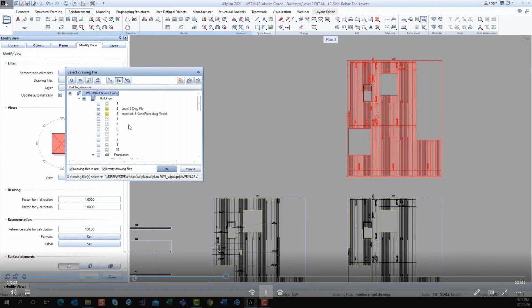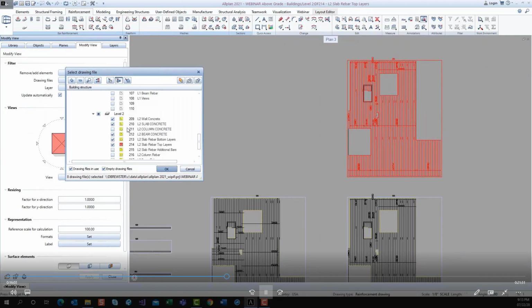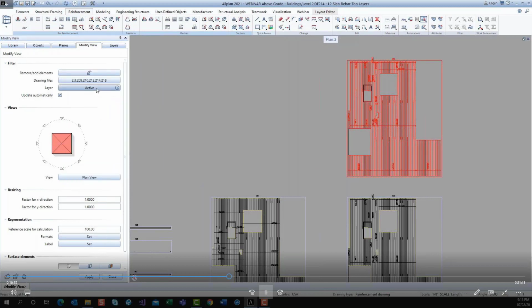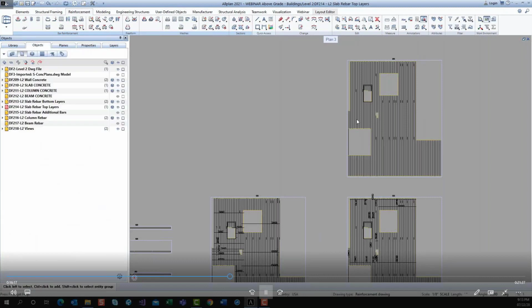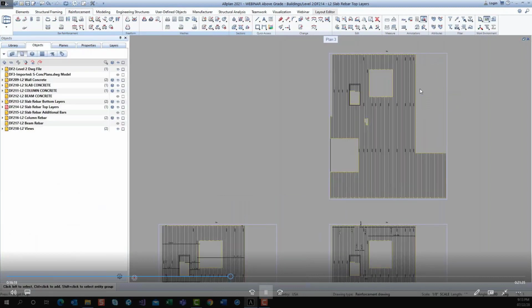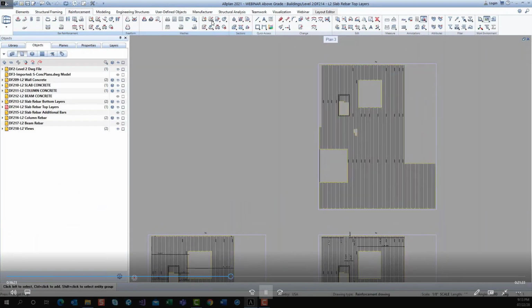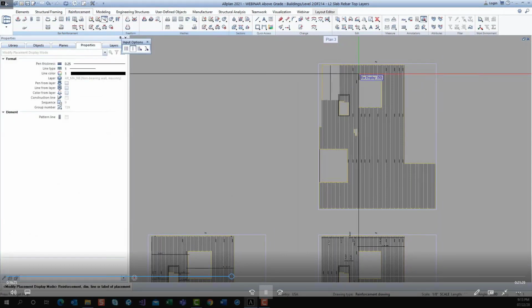The beauty of this particular tool is that at any time I can go back into that tool and modify spacing for the whole mat. I can change the size of bar for the whole mat, but I also can change it individually for each one of those ranges that apply. As a general rule, it's being placed as a mat, therefore you try to modify it all as a mat, but we're not forcing you to stay inside of that.